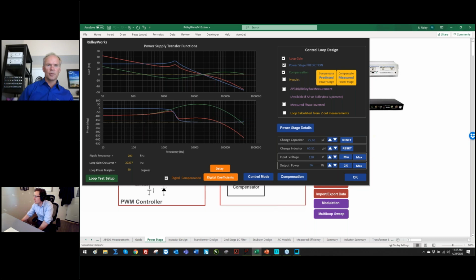Just a warning there for everybody: don't look to Psim or anybody to give you the code to put into production. It's there to do the simulation of functionality. Code is worth what you pay for it. If you got free code, you better not ship it. It needs its own due diligence. To that point, we've had people maintain handwritten code and Psim generated code, and they've given up on the handwritten code after they've gained confidence with Psim generated code, because Psim generated code is purely a conversion of the control. We're not handling the other stuff.